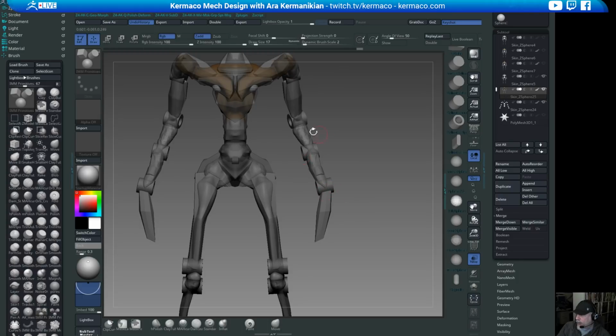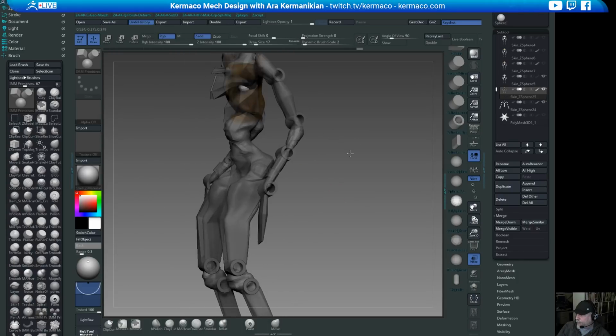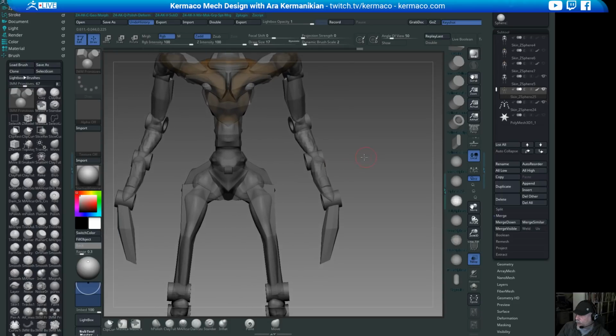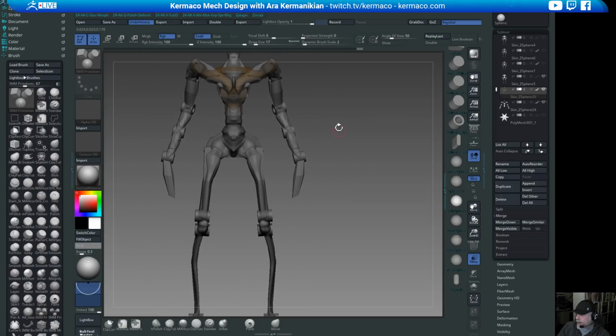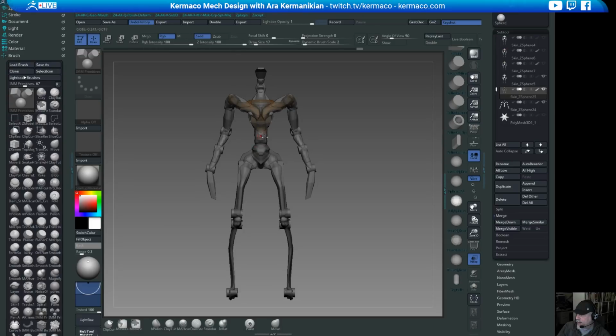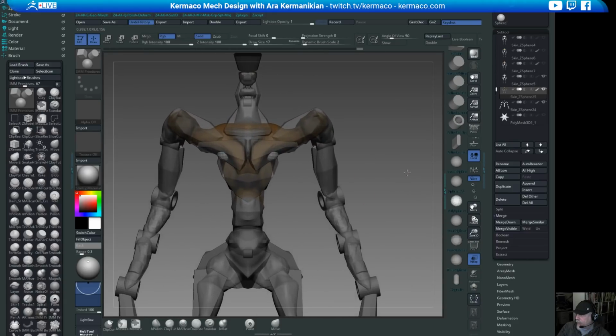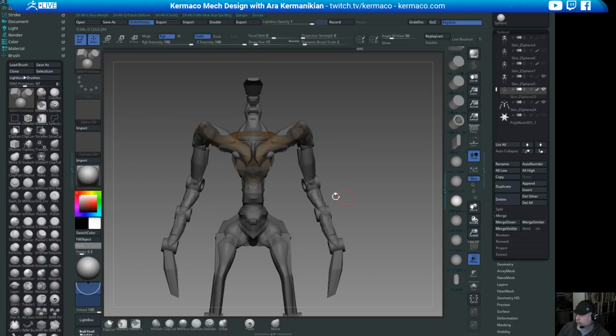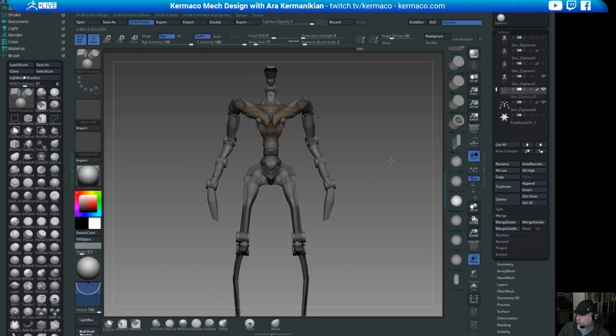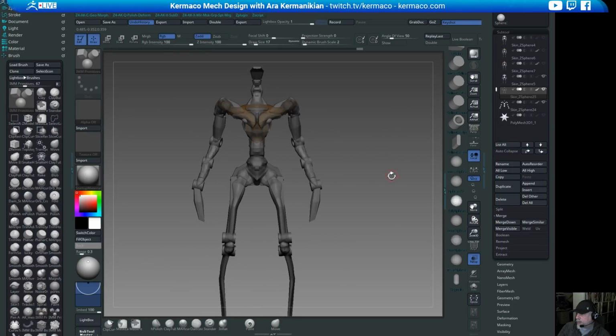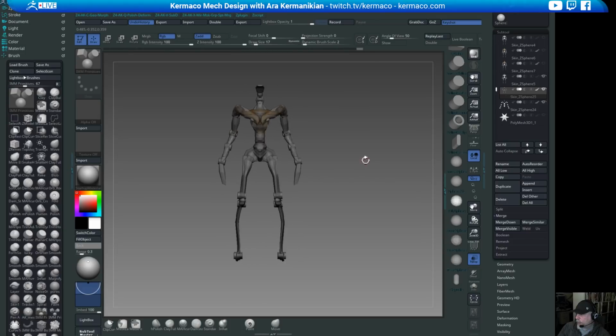It just means that each one of these is going to be its own motor, basically driving this component, and then the rest of the body is all going to be controlled through a processor that makes these things move independently. So if you kind of know what flying by wire is in an airplane, where all the different ailerons and everything independently operate, but are connected through some sort of a CPU, we're doing a similar type of arrangement here with this robot.